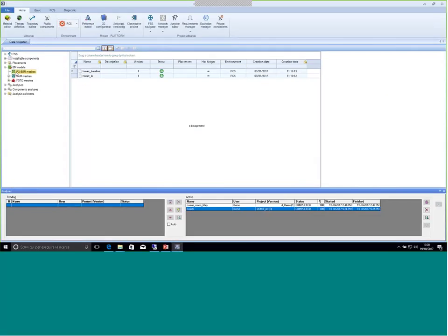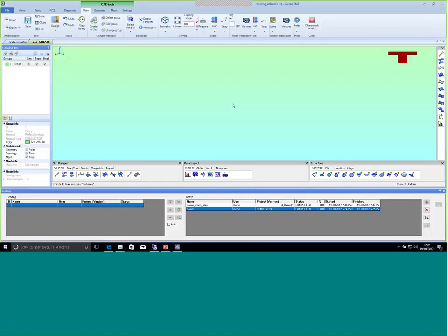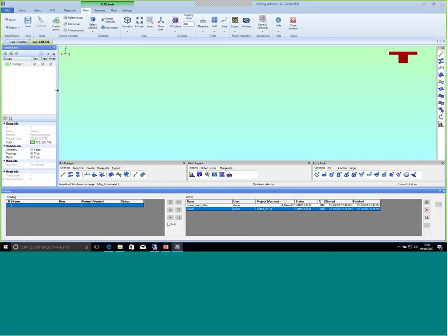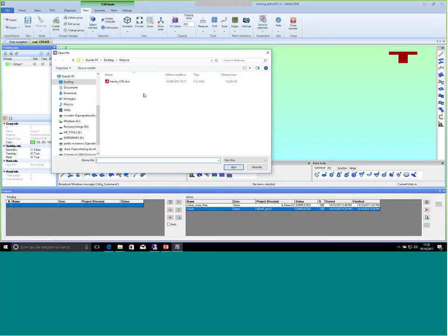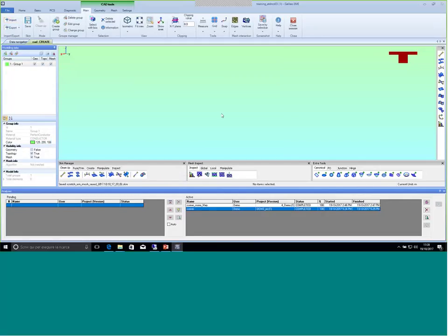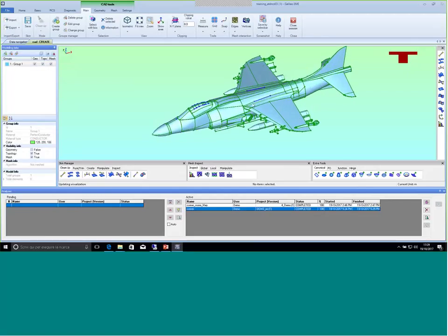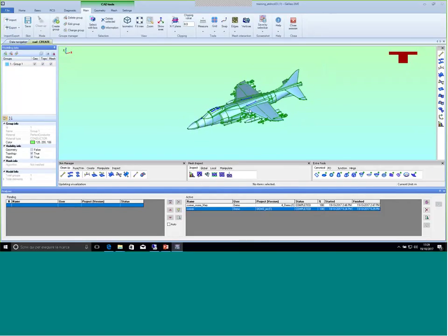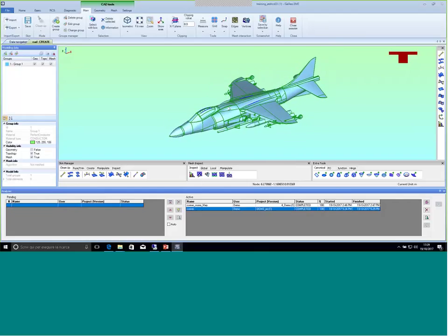Usually, when you deal with a complex platform, you don't draw your model by your own, but you get the CAD model maybe from some manufacturing company. And typically, this CAD model is a quite good mechanical model, but typically, at least in my experience, is not that good from the point of view of the electromagnetic simulations. And the reasons could be different. You could have several reasons for making it a nightmare for the electromagnetic engineer.